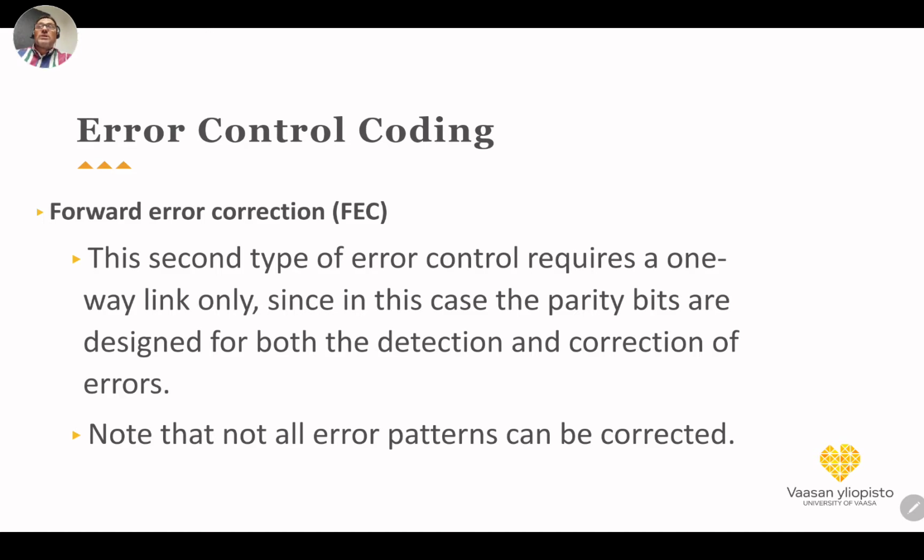the delay, because once the transmitter sends the packet and the packet was not received correctly, the receiver will ask the transmitter to retransmit the packet again, and every time retransmitting the packets can introduce big latency and delay in the network. Also, it increases the competition, especially in contention based networks. It will increase the competition for the retransmission, and it will delay many packets, not only for that pair but also for the other users in the channel.